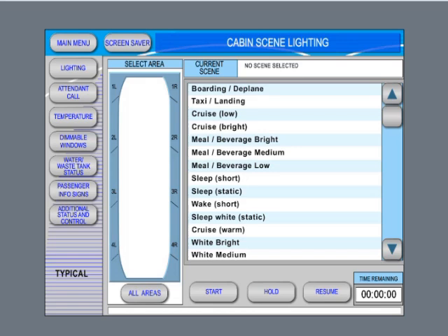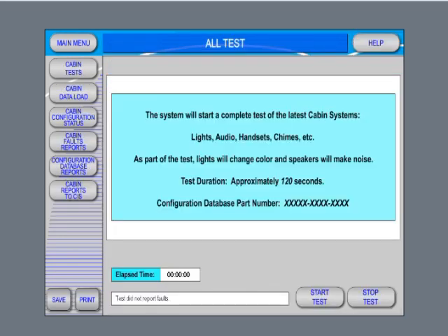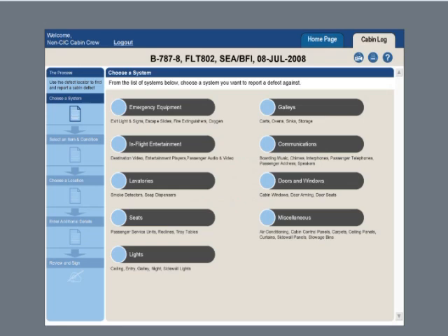You used the CAP menu to control the cabin lighting and see non-normal indications. You used the CAP Maintenance menu to identify system faults and did Cabin Services System tests. You used the menu selections to identify and change the CSS software configuration. You used the CAP Cabin Applications menu to identify the cabin log entries or the selections to make an entry.